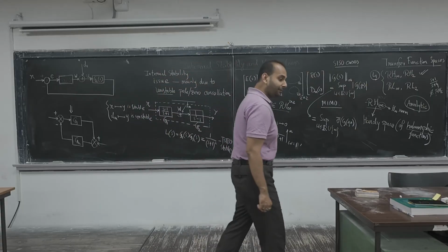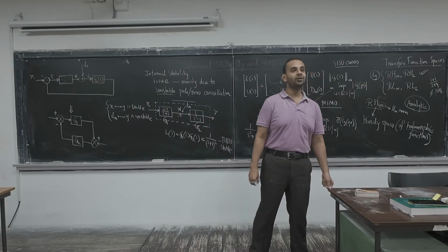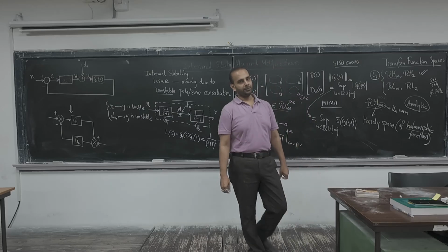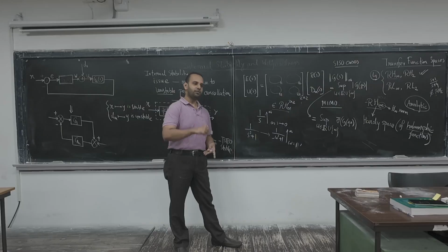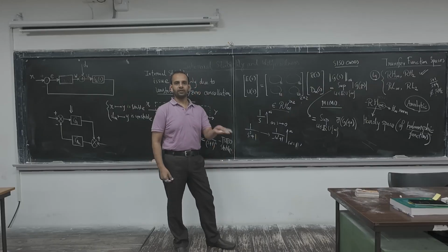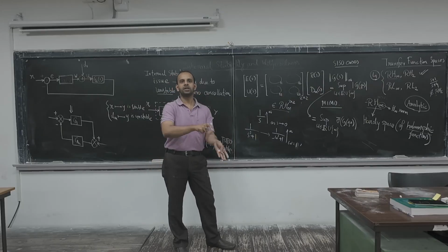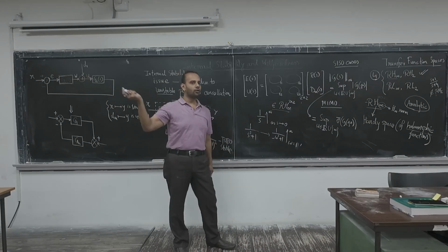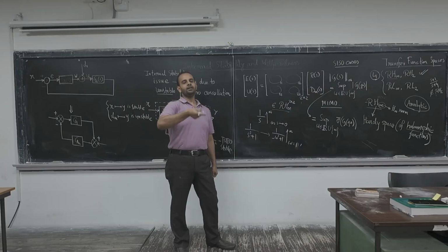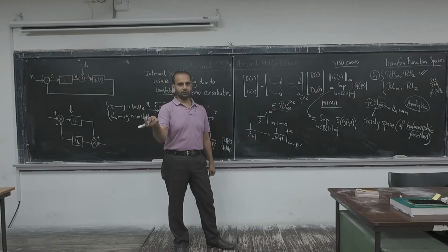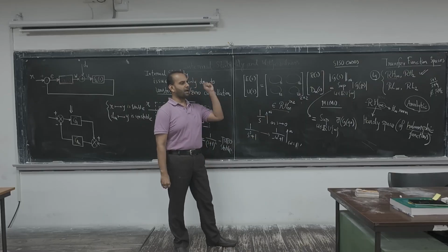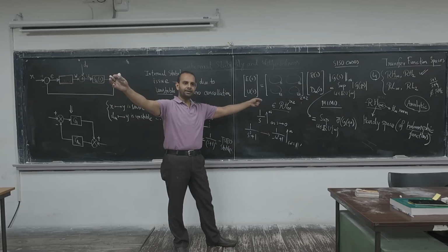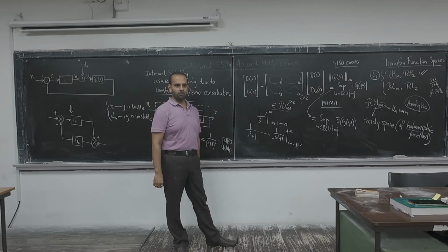Because in the time domain, it is really difficult to talk about the gain. So whenever we analyze the gain of a system, we first convert the time domain expression into a transfer function, then we check the frequency response, usually the Bode magnitude plot. So once again, the maximum value over the entire interval is the H infinity norm.